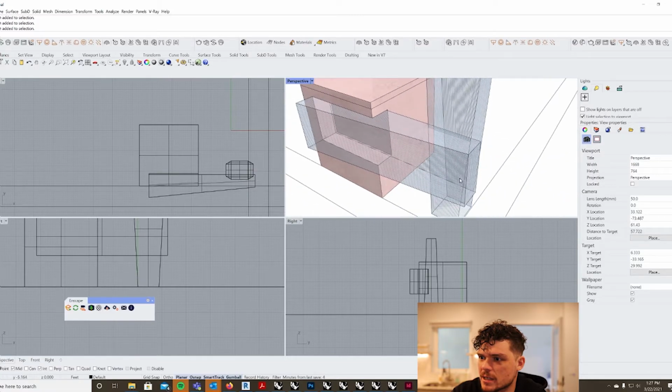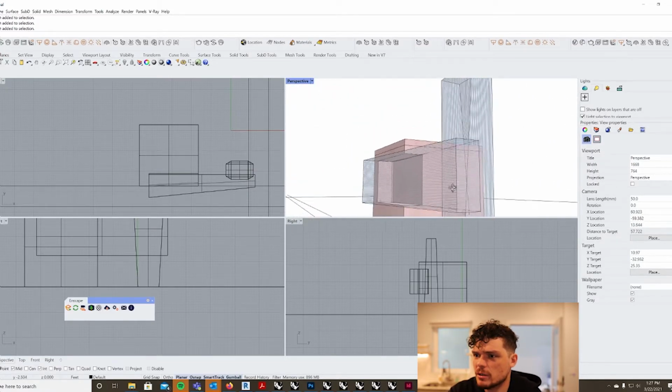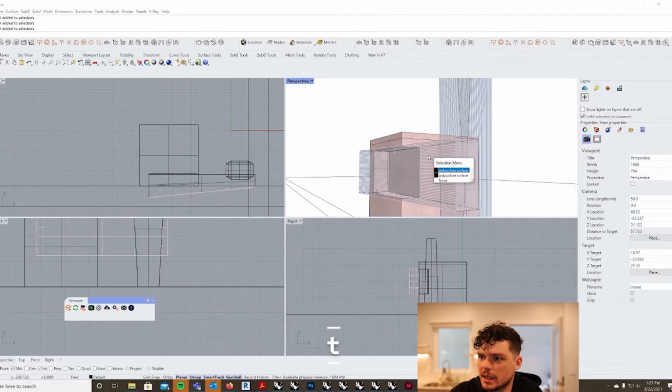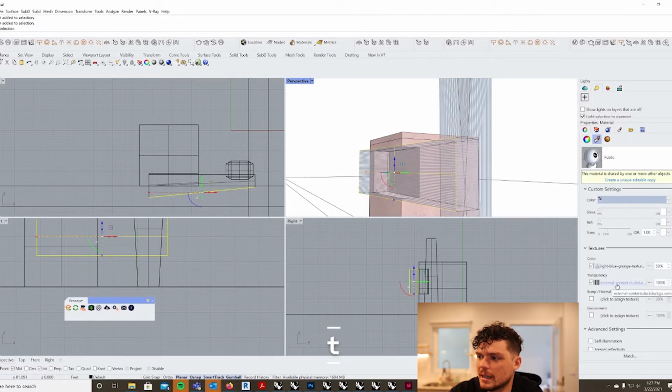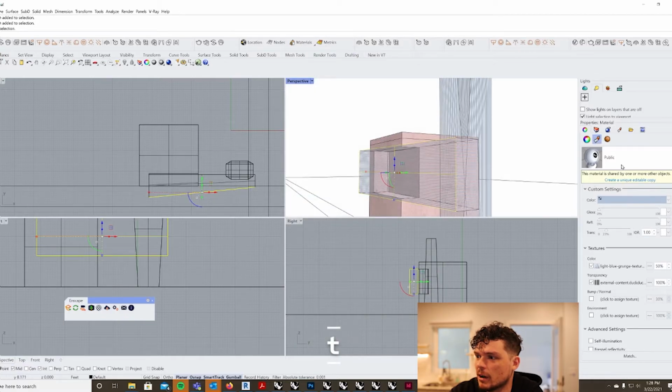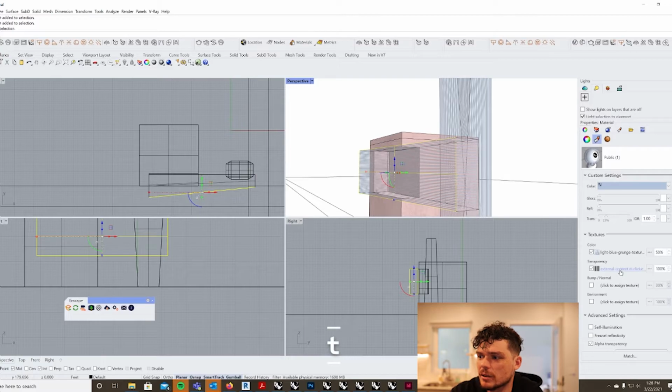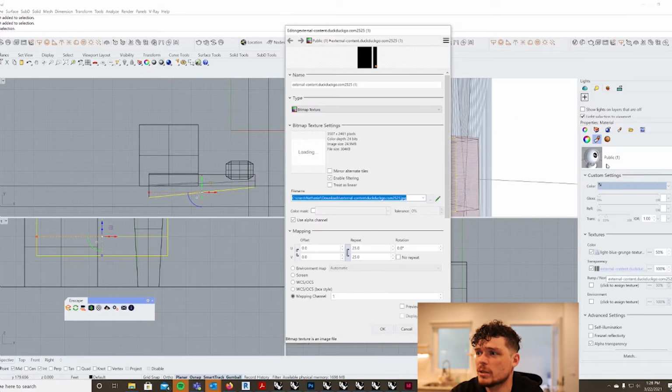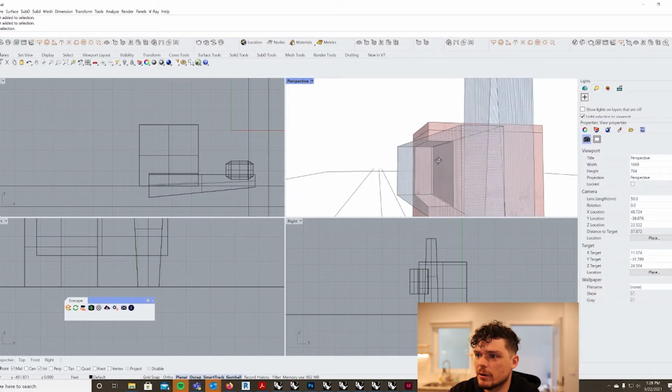Now we're looking at these faces and they're not correct. So what you have to do for this is Control-Shift and select the face itself. Now, I can't just rotate it and hope that it's going to be better. Unfortunately, I have to create a unique editable copy. So you have to copy the material. Now I can select this. Now I'm in a new material called Public 1. I would probably want to rename it so I really know it's a different one. And I'm going to rotate this 90 degrees. And you'll notice that that rotates now.